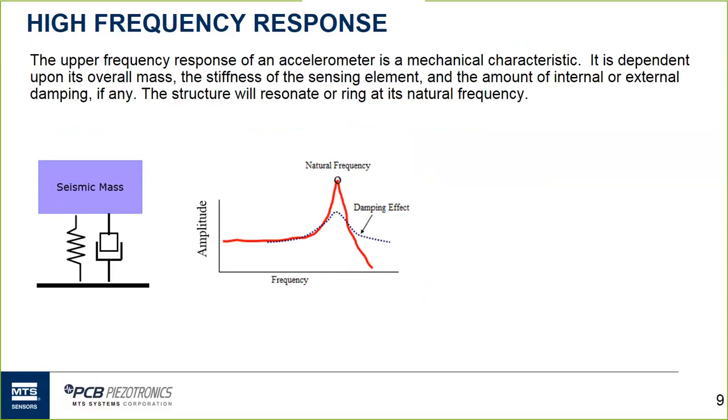And that will provide filtering of high frequency content that typically is undesired, or depending on the sensor technology, could be allowing to mitigate some of those other undesired characteristics that you may not want to see. So ideally, looking at the plot to the right of that, we have a plot of the natural frequency of an accelerometer relative to amplitude and frequency.